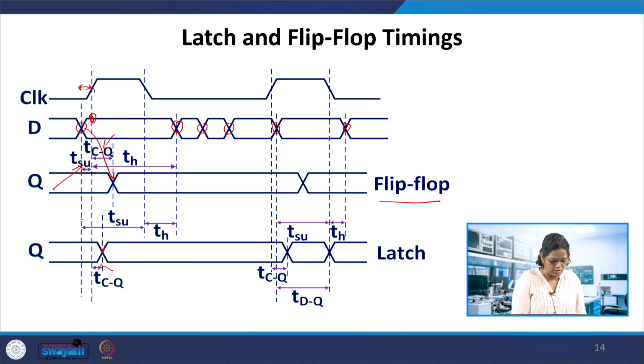So the clock to Q delay is this, and the setup time is from here to the negative edge of the clock, when the clock is inactive. So there is a difference between this setup time and that setup time. And the hold time: after it becomes inactive, how much time it takes for the data to be stable. That is TH.